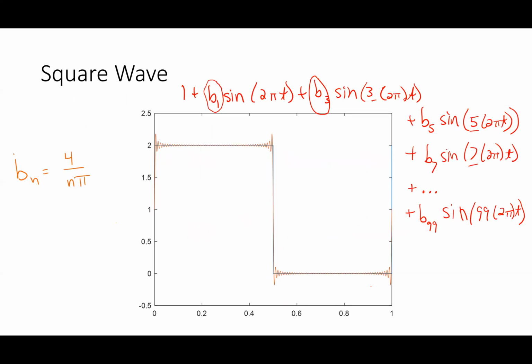All right, so what I showed at the very beginning was, if you've got a square wave, the square wave is the simplest thing to do. And I said, if you added up sine waves, particularly sine waves, not cosine waves, that had these harmonically related frequencies. What I showed previously was I had something at the fundamental frequency, which in this case is omega equal to 2 pi. And then I've got something that has 3 omega naught and 5 omega naught, and so on and so forth.